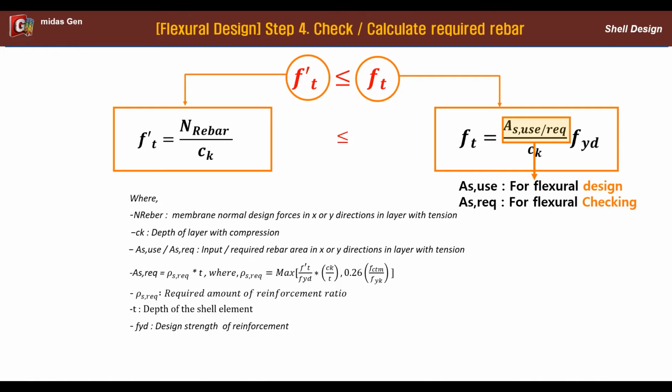If the shell has reinforcement information using user input for flexural checking, the amount of rebar, AS use of the shell, can be calculated instead of AS requirement.